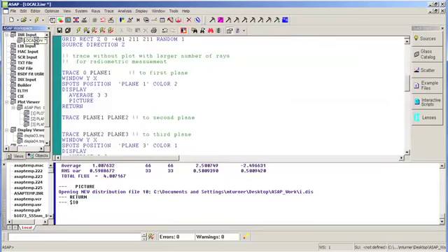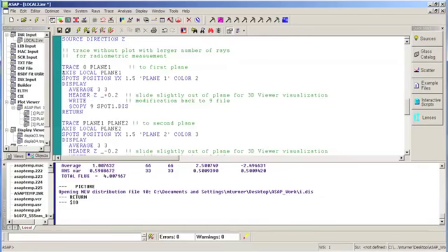And that's actually quite easy to do with ASAP. It just requires a different command. And the particular command we're going to use is what's called the axis command. The axis command, in particular with the local modifier, allows you to change the orientation axis for your next calculation, in this case, the spot's position command. What our axis local, in this case, plane 1, is saying, for the spot's position command, define a window that is defined based on the local coordinate axis of the defined piece of geometry, plane 1. So now we're going to define our analysis window in the coordinate system of plane 1.